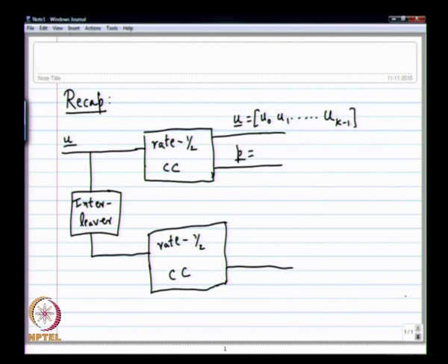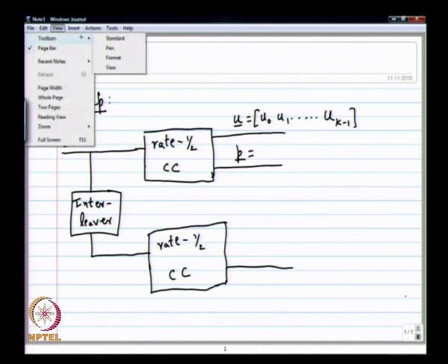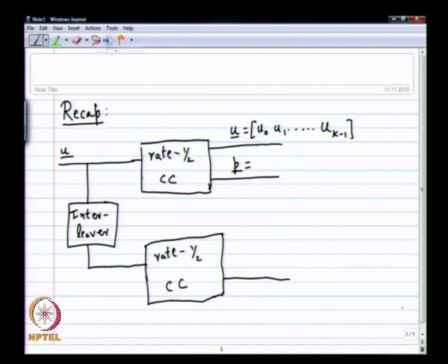Okay, so maybe you want to terminate it. I might decide to terminate the first one, in which case you would get the first parity sequence. Okay, if you are terminating the second convolutional encoder also, then you will need some additional bits that will have to be added to this. If you do not add it, then you are not terminating the next one.